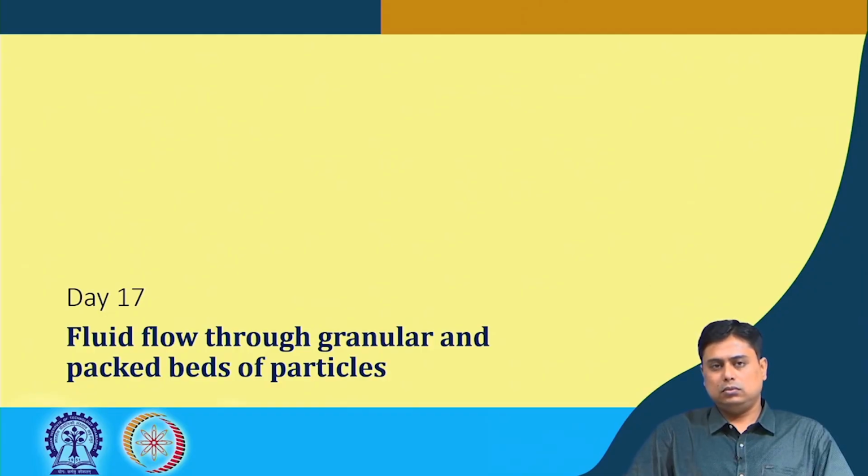We have seen the pressure gradient for laminar flow through a bed of material, as well as for turbulent flow, and how we can estimate the pressure gradient across a stack of material, particularly mono-sized spheres.